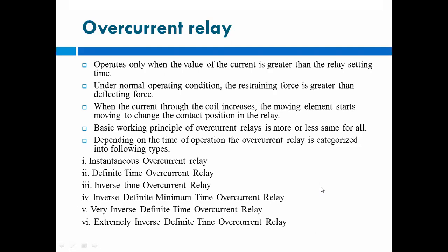When the current flowing through the operating coil increases, only then will your relay start operating. Otherwise, the restraining force is more than the operating force, also called the deflecting force. So, different times are required for the operation of that relay. According to that, depending on the time of operation, overcurrent relays can be divided into different types.